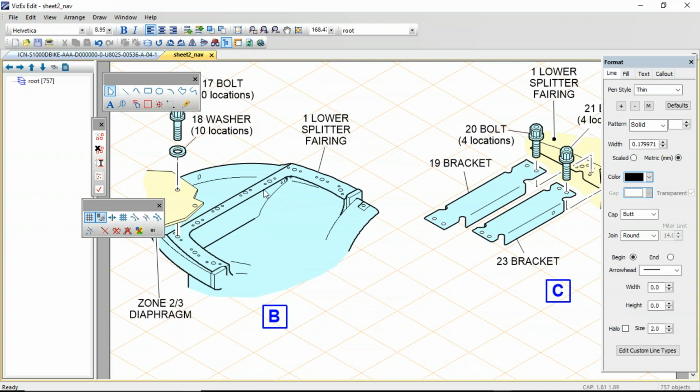Line weights, I've noticed that this has probably come from another piece of software. We can see this darker or thicker line is 0.347, so it was obviously a 3.5, but it might have been in the export that it's not done with the accuracy turned on. Also the 0.18 is now 0.1799, so it's very, very close, but obviously not quite 0.18. But it would probably pass. In my experience, there's no real way of validating this other than actually opening the file and looking at it. But I would say they're obviously close enough. They're within a margin of error.